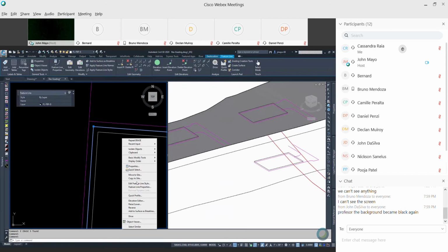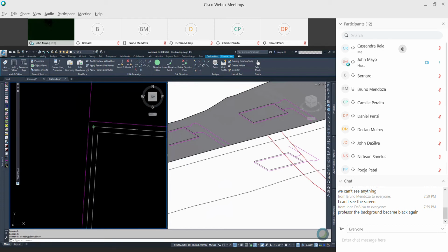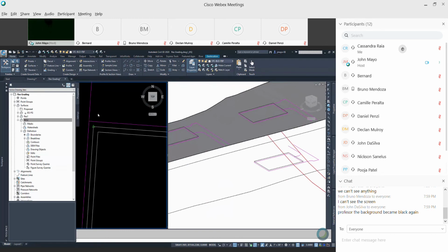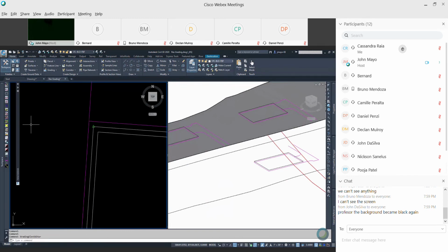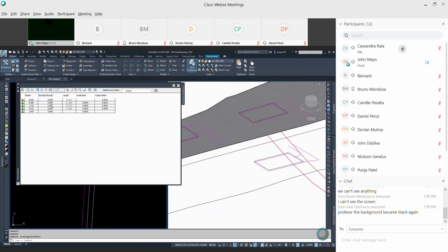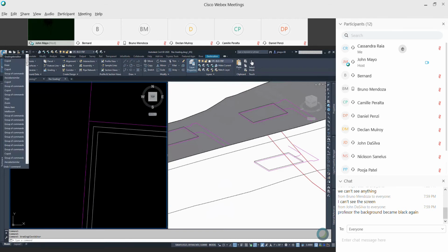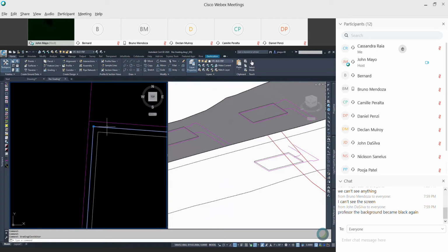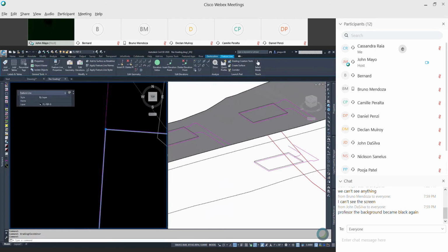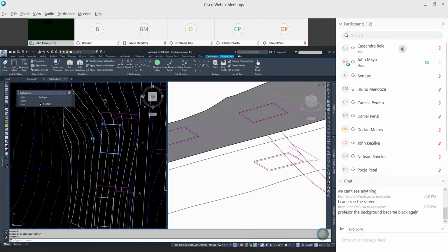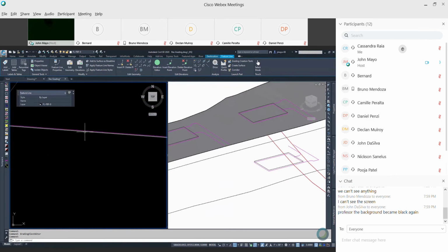All right, if you want to know where your elevations are, you can label your feature lines and or polylines, or you can use the elevation editor, which shows up in that panorama thing that was blocking your view before. And these are actually at elevation 0. So I converted the wrong polylines there. And I need to move this guy up 379. Same thing with this guy.